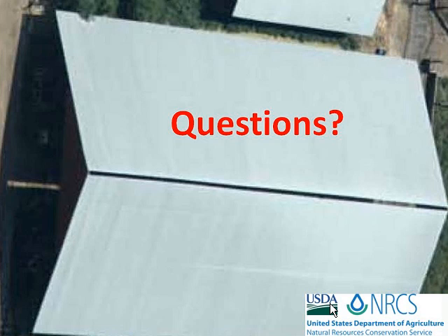I have seen some online calculators, so you could put in the footprint. In any case, here's another good question. It says, what are the required slopes and roughness coefficient for corrugated plastic drain pipes? I guess roughness coefficient. This gentleman, Jeremy, is probably thinking about Manning's equation. I mean, that's a look-upable item.